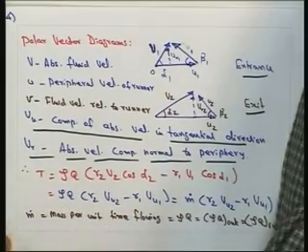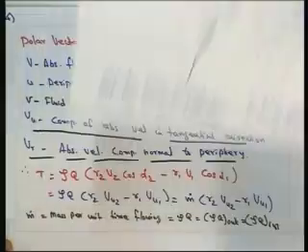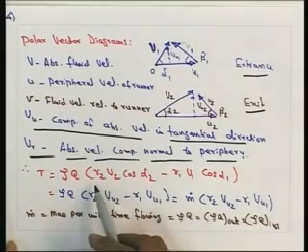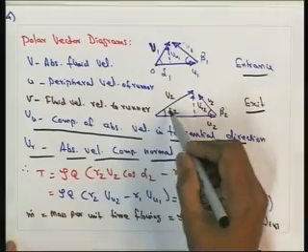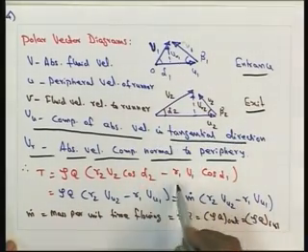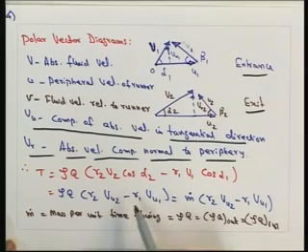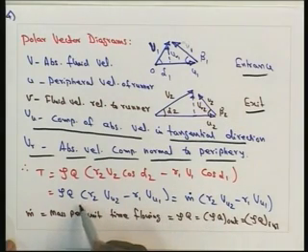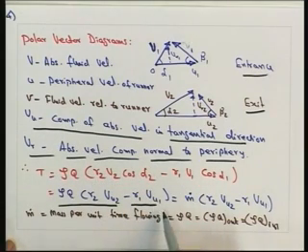Finally, with respect to this system, we can write T equal to rho Q R2 V2 cos alpha 2, and this alpha 2 is drawn here, minus R1 V1 cos alpha 1. That gives the torque for the system, equal to rho Q R2 VU2 minus R1 VU1.